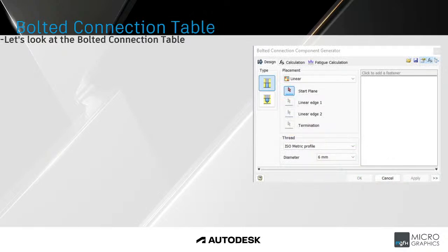Okay. When you select the bolted connection, the table on the right will appear. Like you can see here, you've got a few options you can choose from. So let's look at the difference. First we've got the type. You get two types, your through-all connection type and your blind connection type. A through-all connection type goes through all holes or drilled through all the material. A blind connection type is where the last hole is blind.